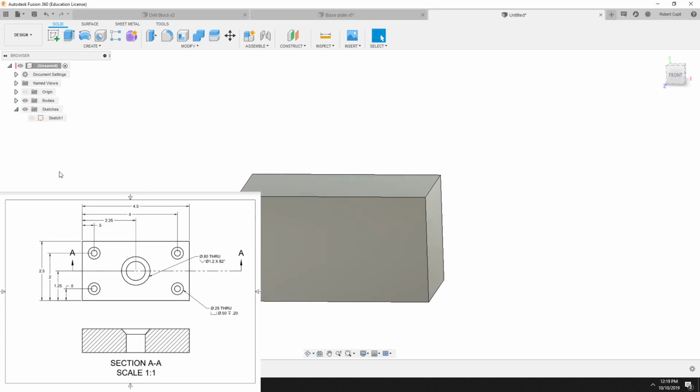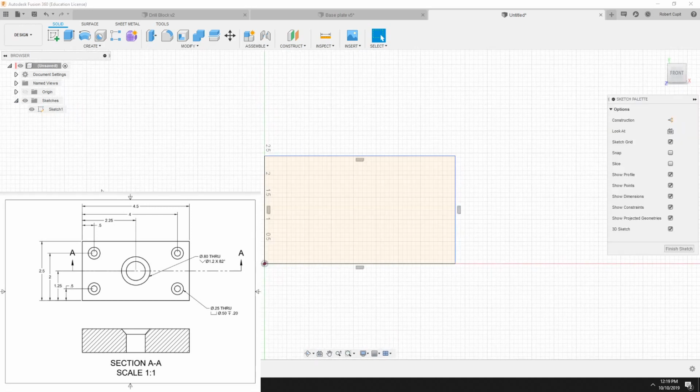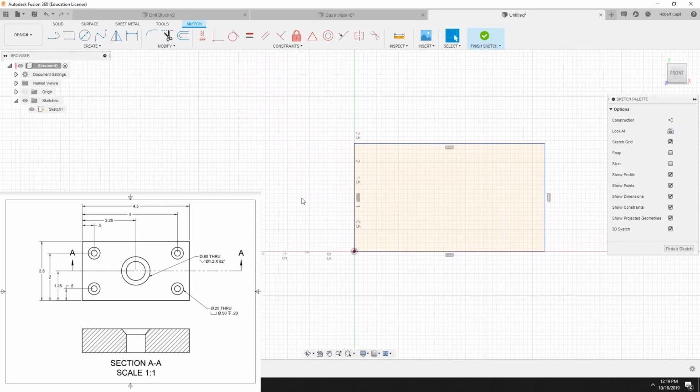The problem is with this block, you are going to go back into that sketch, and you're going to need to make, and you can see in the drawing over here, that I have all of the dimensions that I already plugged in. You need to draw where the holes are going to go. For example, I have now a point on where that hole is going to go. I'm going to draw another line using the dimensions. I'm not putting the dimensions in, but you will be. So I've got 2 little dots. I've got a hole there and a hole there that I could put.